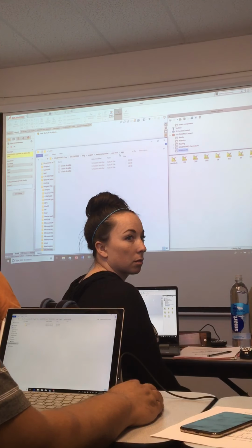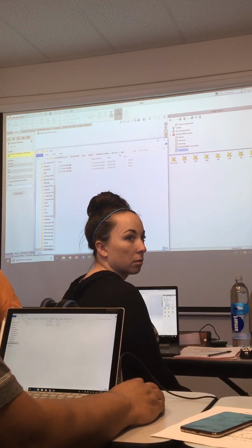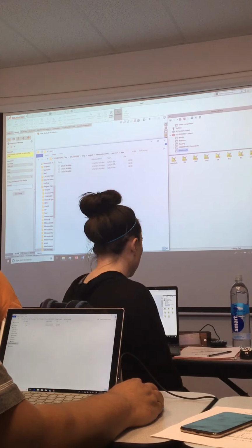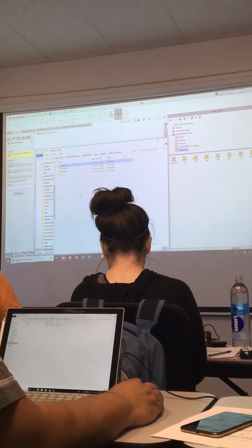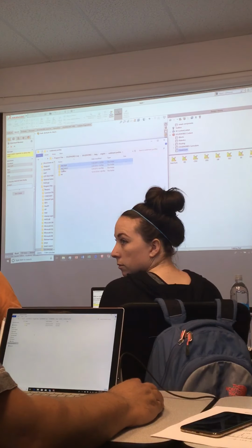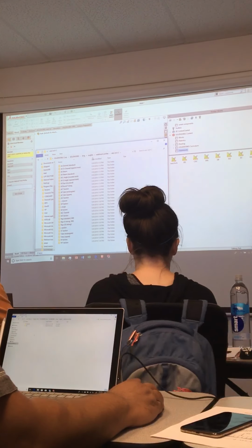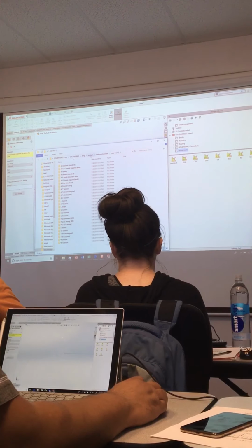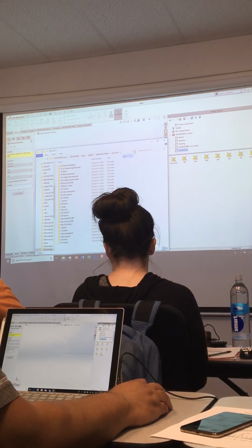Okay, but when we save it to this file, are we saving it to a folder or inside that? Where are you saving it to? Well, exactly. What we want to do is save our ANSI2 thing here, which is this one here. See, this one wants to get saved to this directory: SolidWorks Corp, SolidWorks Lang, English, Weldment Profiles, and whatever name we have.